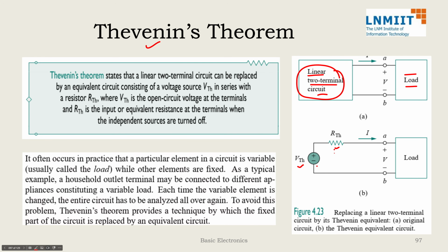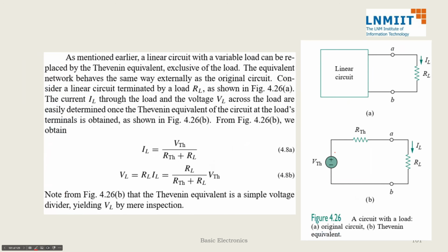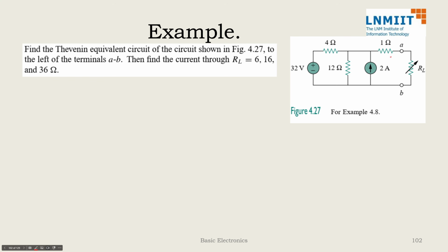So now we need to find, if I have a circuit with me, so something like this is my load resistance, then what is the Thevenin equivalent for this whole circuit between point A and B? So we need to identify two quantities. One is VThevenin, one is RThevenin. To find the VThevenin, just open the circuit between A and B. VThevenin, for the same reason, is also called V open circuit. Just open A and B and apply KCL, KVL, anything, and find the voltage between A and B. That will be our VThevenin.